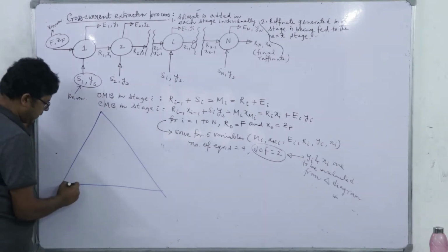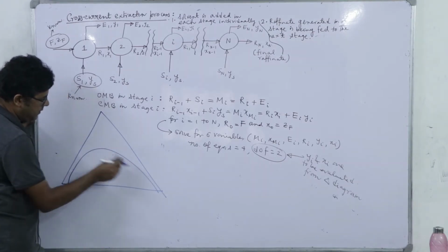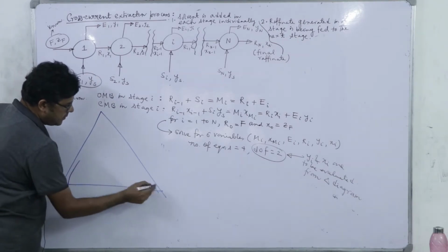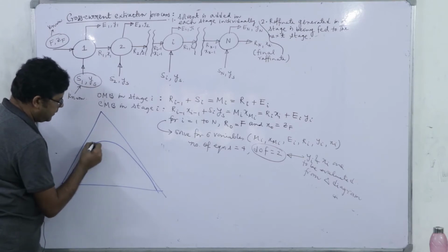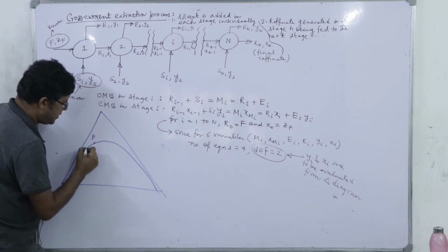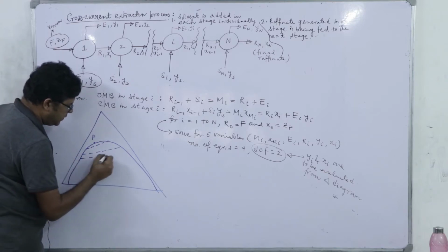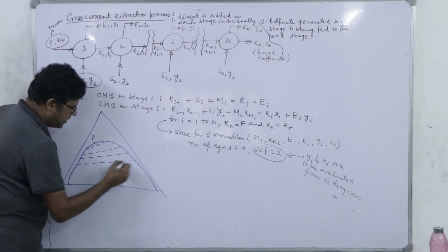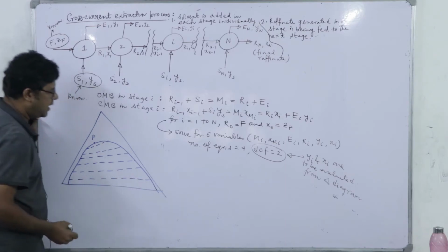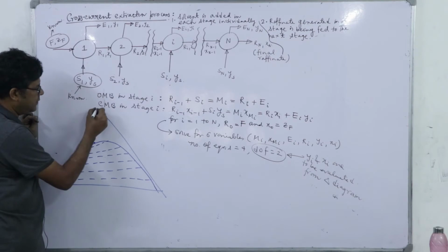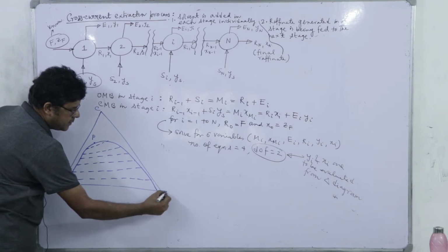So we draw this binodal solubility curve, and let's say this is the plate point, and these are the tie lines which we have used, and this respective equilibrium data we have used in drawing this solubility curve. So this is C, this is A, this is B, right?